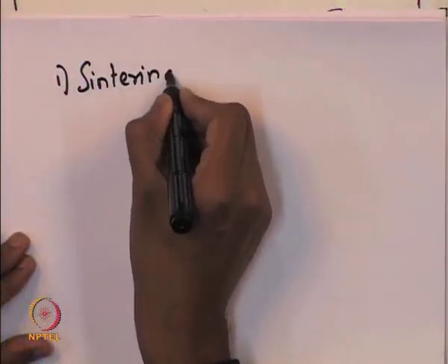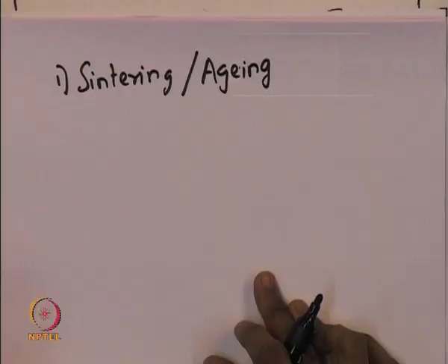Let us take the sintering method of deactivation. Sintering is basically the deactivation of the catalyst because of the prolonged exposure of the catalytic sites to the reactants in the gas stream. Because the reactions are conducted at a high temperature, the metal particles which act as a catalyst and which are impregnated on the catalyst site leave the catalytic sites and start agglomerating together. As a result, the net surface area available for the reactants to adsorb onto the catalytic site significantly reduces, and the catalyst activity is completely lost.